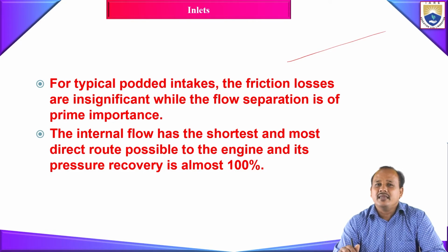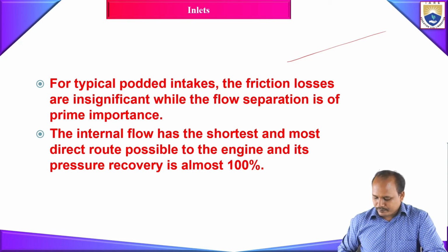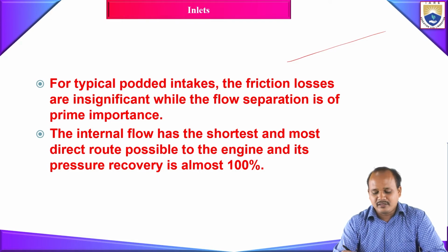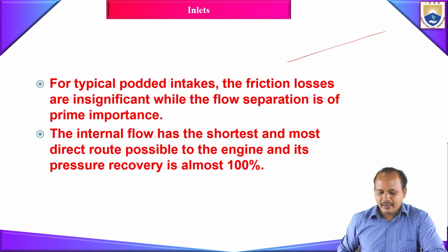As such, the loss created due to friction is small, but the major source of loss in your intake is going to be flow separation. So you can get close to 100% pressure recovery factor for your ported intake.